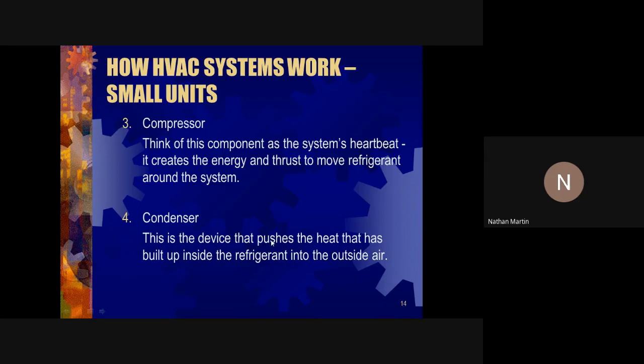So, for persons who don't know, the refrigerant does not go to the radiator, right? It goes to the condenser, which is found in front of the radiator if you are looking from the outside. And right beside the condenser, a lot of times you'll have your dryer, right? And that is used to remove moisture from the system. All right.